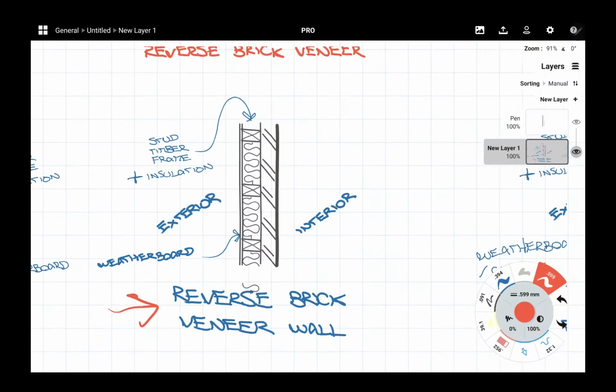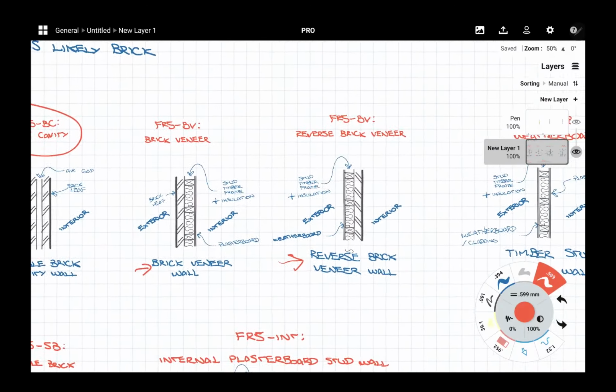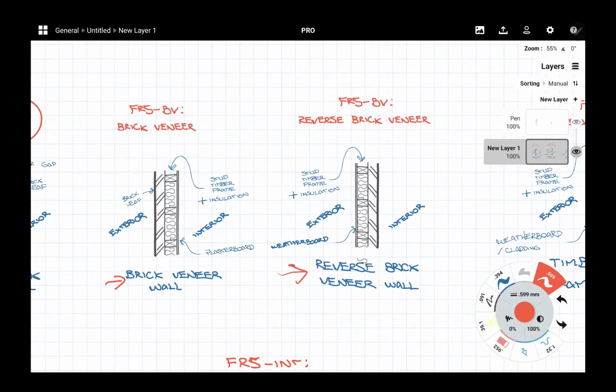Meanwhile, the internal brick layer has higher thermal mass, and it's able to absorb and store heat and then re-release it at a slower, sustained pace. And so it helps to stabilize the internal temperature while resisting very high or very low external temperature. So that's why these two types of walls, which are literally the same but flipped, perform differently.